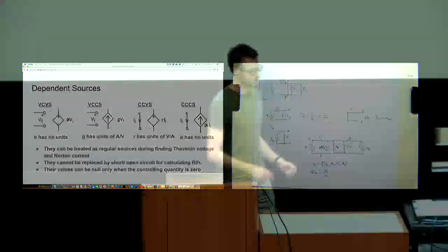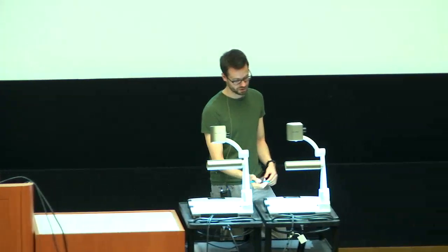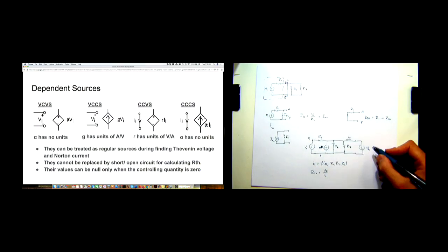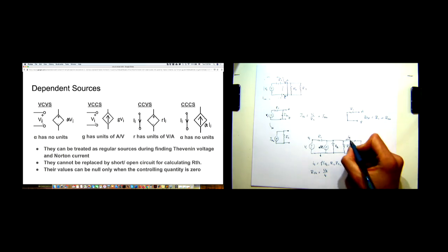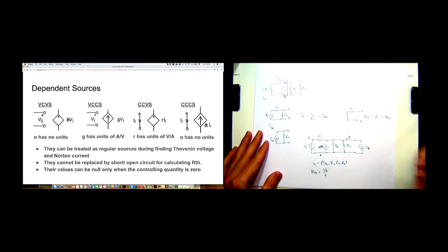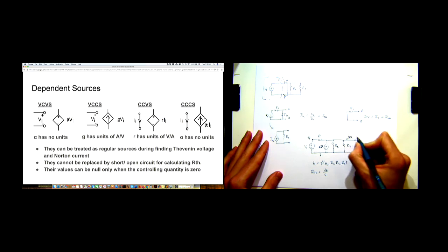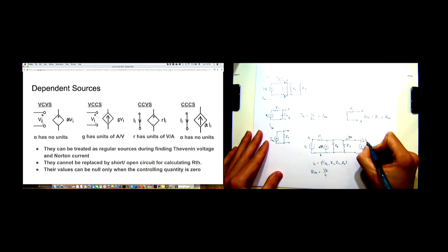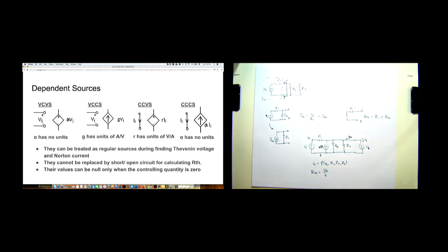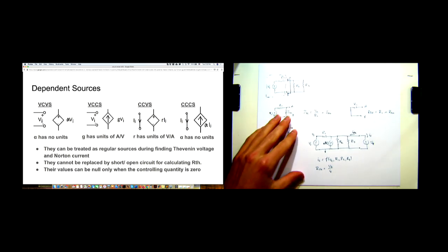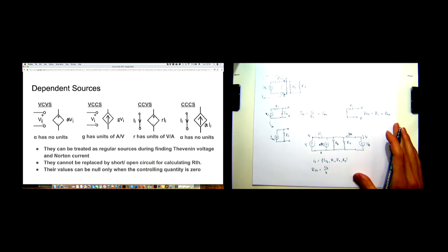No, it's not pointing. So basically, let's call this V element. So if we call this I element or something, this is I test. Okay, are you happy now? I test is going to be equal to minus I element. So it's opposite to passive sign convention. Just remember that.